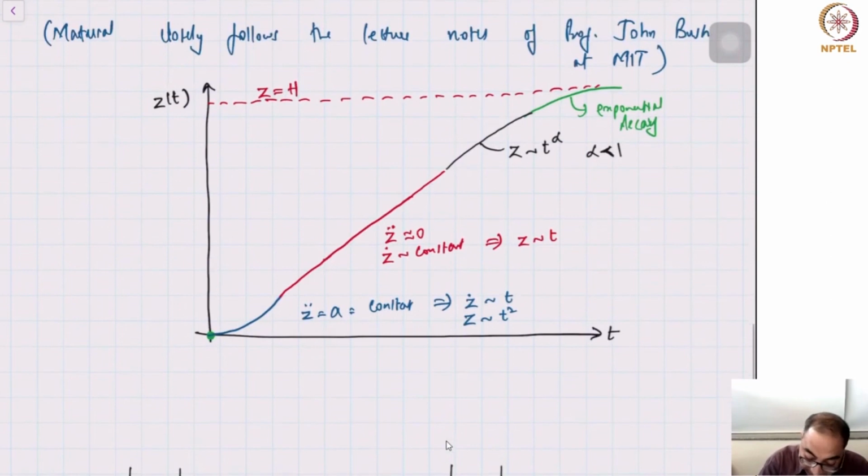Therefore, you can actually say that the first region here is inertia dominated, and these two regions are viscous dominated. Note that surface tension is present throughout. So you're going from an inertia dominated region, where inertia becomes less and less important because the fluid is slowing down, and then you enter a viscous dominated region. And the viscous dominated region, again, you can sort of divide into two parts. I've shown them in black and green curves. So we will look at each of those regions.